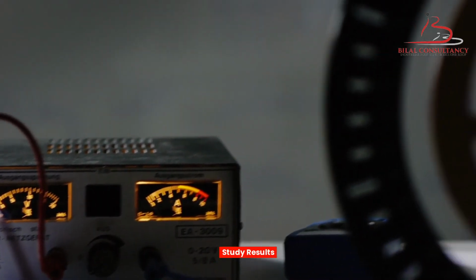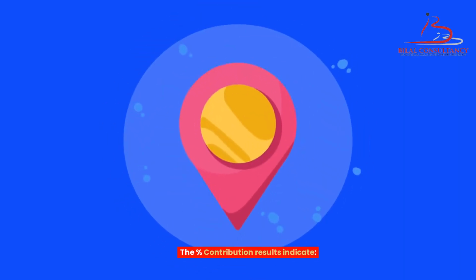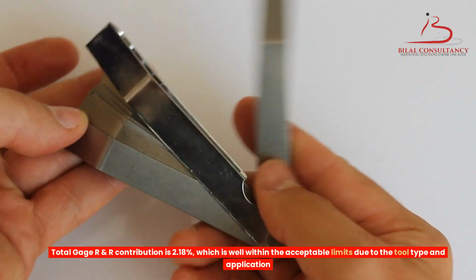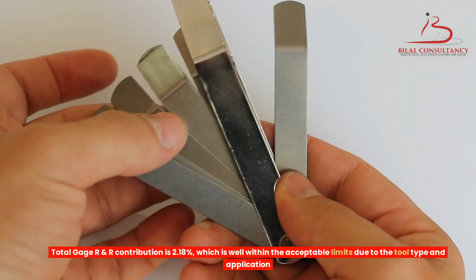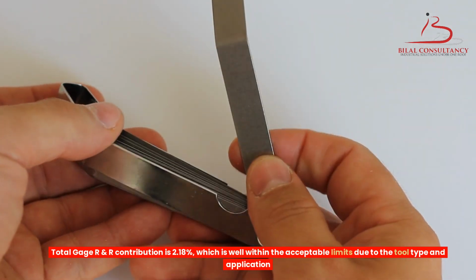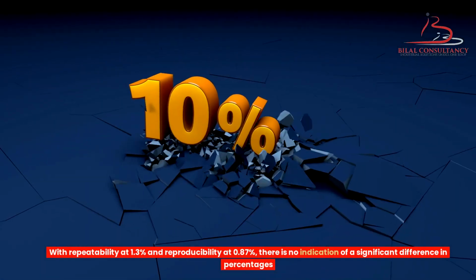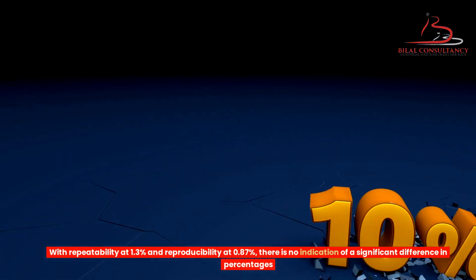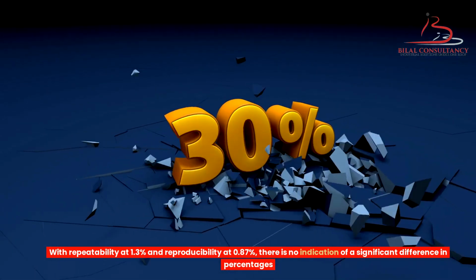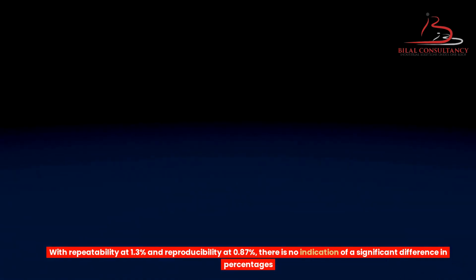Study results. The percent contribution results indicate total GageRnR contribution is 2.18%, which is well within the acceptable limits due to the tool type and application. With repeatability at 1.3% and reproducibility at 0.87%, there is no indication of a significant difference in percentages.